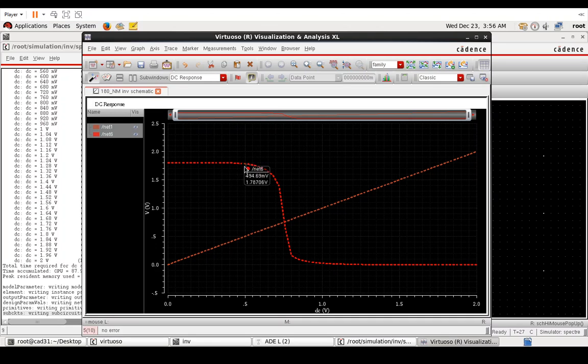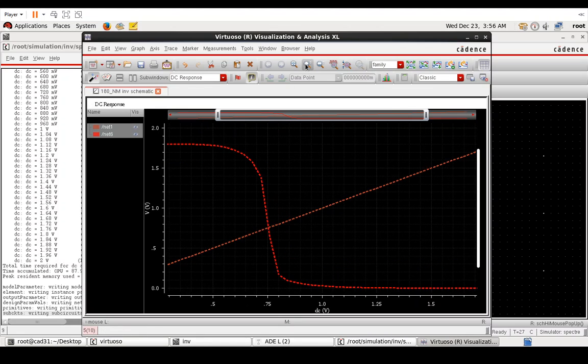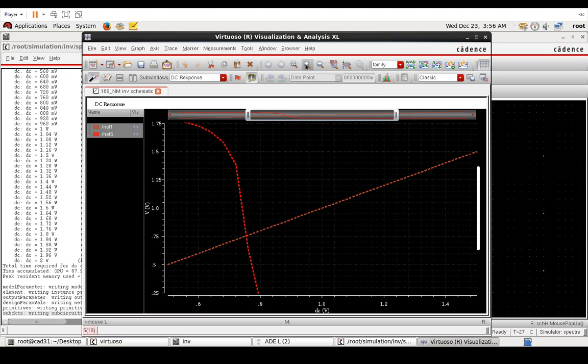This is the voltage transfer characteristic, also in the theory the ABCDE curve, and this is the input versus the input, so it's just the x equal to y line, and where they intersect is the inverter threshold voltage. That is a point where the input voltage given to the inverter comes as the output voltage.